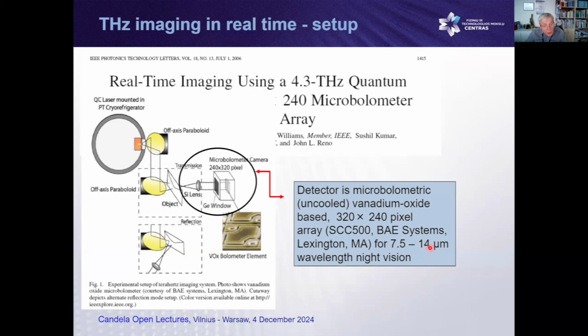If you look at the numbers here, it's a purely infrared camera. It means they have a protection layer on the top, and they were able to remove it to increase absorption, because bolometers work regardless of which kind of source they used, since they feel the heat.